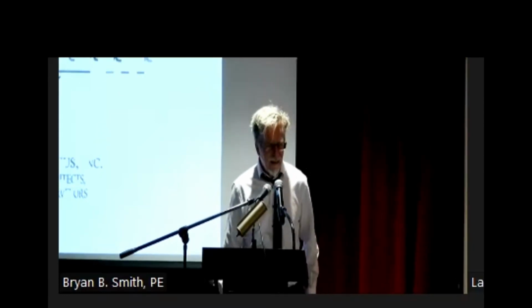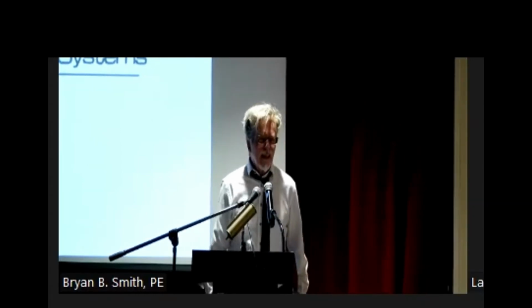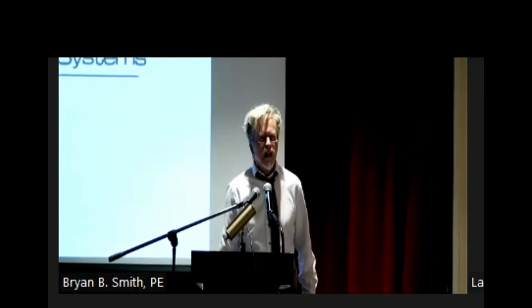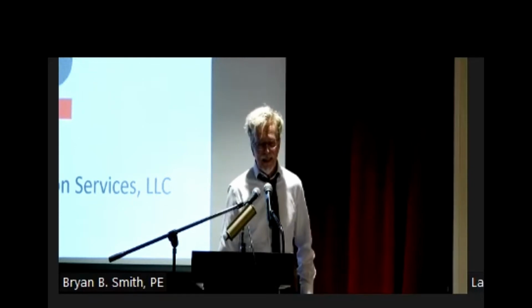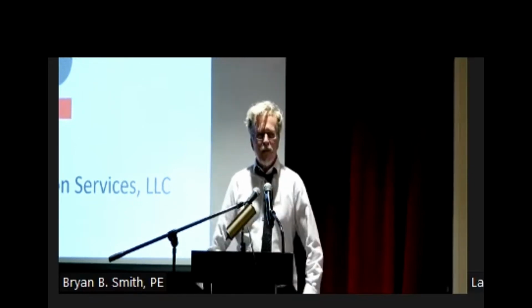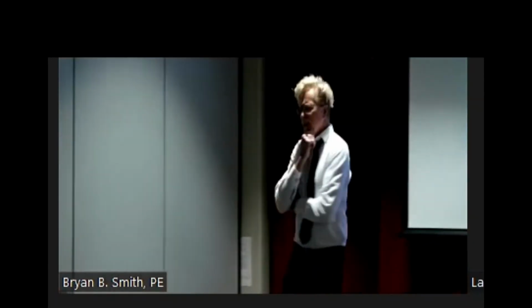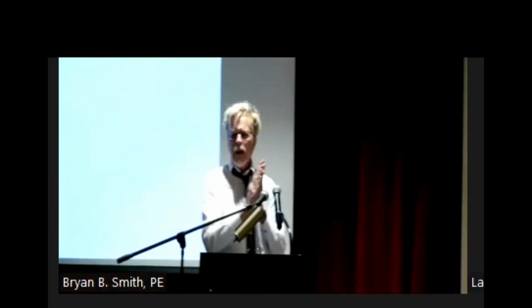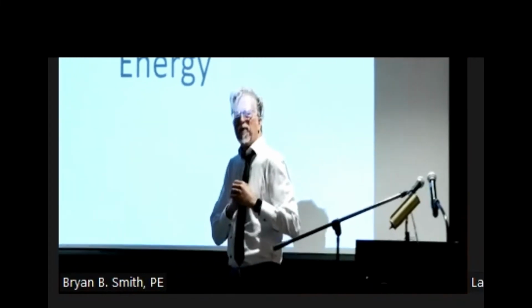And then everyone ran out of the pump station because when the check valve allowed for a reversal of flow and closed, the pressure hit 273 PSI. Okay. And then what's to follow? Well, where are we over here? Oh, there's negative wave and then a positive wave. Same thing with closing a valve. I am a positive wave. Now what's going to happen? Now I'm a negative wave going down the piping system.